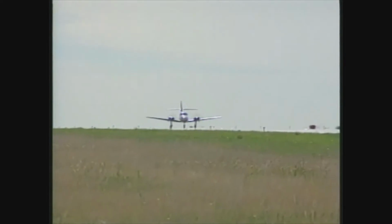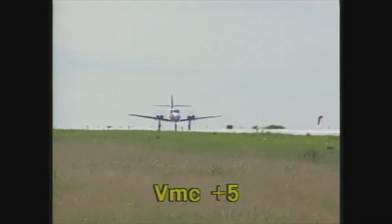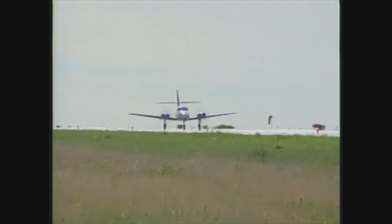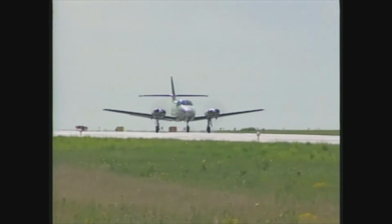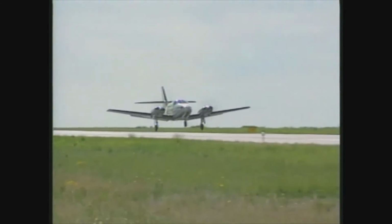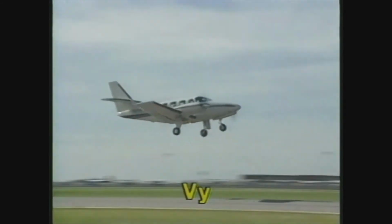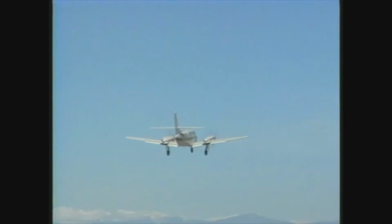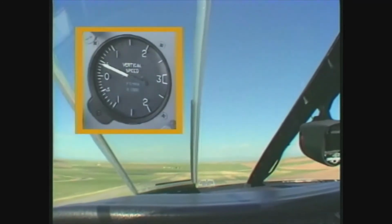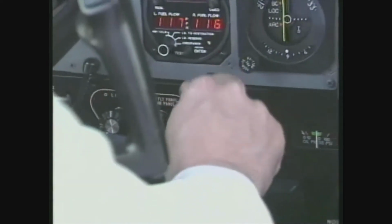Accelerate to the recommended liftoff speed, or VMC, plus 5 knots, whichever is greater. In any case, never allow the airplane to become airborne below VMC. After liftoff, accelerate to the best rate of climb airspeed, or VY, and maintain that speed for the initial part of the climb. Retract the landing gear when you have a positive rate of climb and can no longer land on the remaining runway.